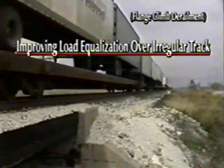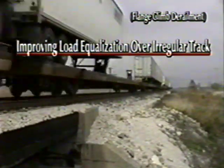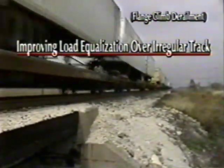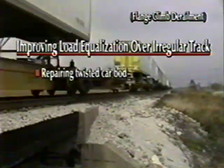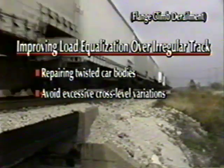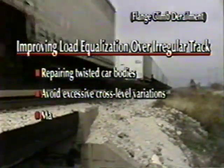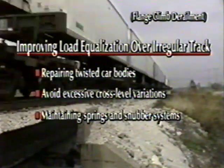Let's review the factors that will reduce the chances of poor load equalization during operations over irregular track, like repairing car bodies that are twisted, avoiding excessive cross-level variations that cause undesirable track twist, and maintaining snubbers and springs in the truck.